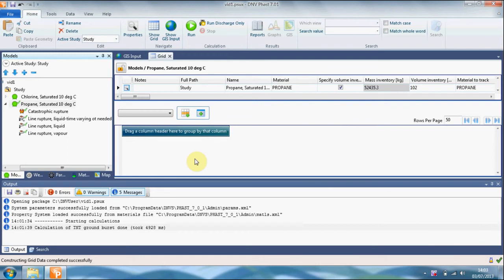We will now look at alternative methods for modelling early explosions. When you were setting the input data for the flammable scenario, you left the flammable tab section with the default settings, which means that the early explosion for the rupture scenario was modelled with the default method, which is the TNT method. In this section, you will create a version of the rupture scenario that uses the other methods for modelling early explosions and compare them.